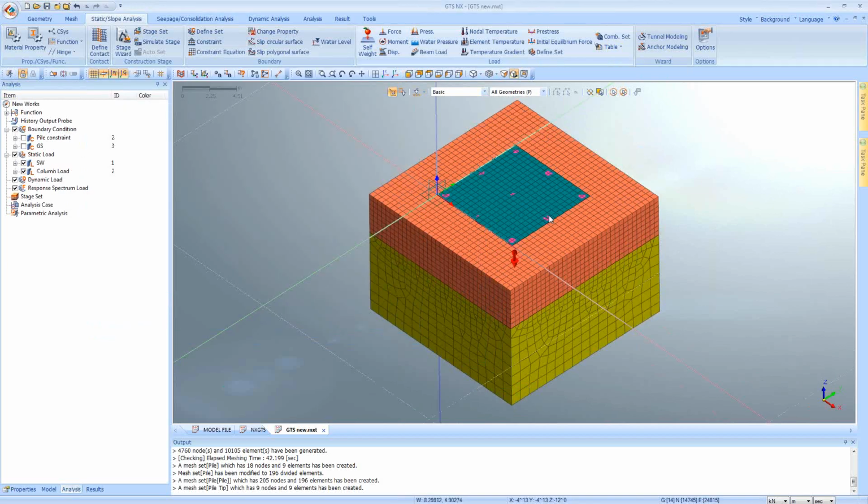So you can see that automatically at this location the nodal load or the reaction from the column has been imported. So next time if there is any change in the value, you can just change the value in the Excel sheet and directly import. So you need not create a model or manually define. For example, right now we have 9 columns. Original model files can have 100 of columns. So at that time this feature will become very efficient.